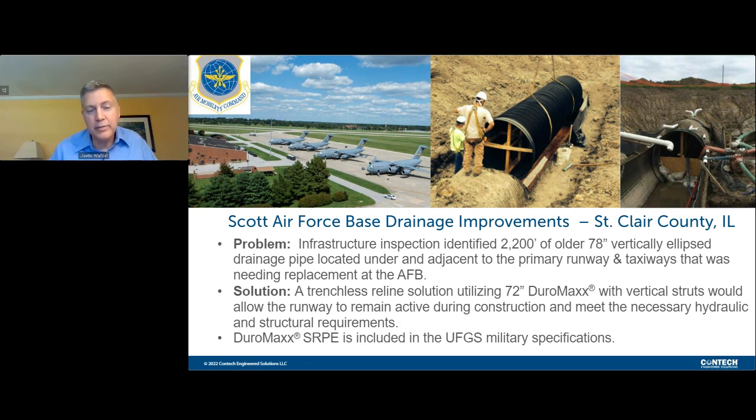Now, the liner pipe is less square foot open area than the host pipe, but because the Duramax liner has a smooth interior and the host had a corrugated interior and the overall system was acting in outlet control, the hydraulics did not suffer from this reline.